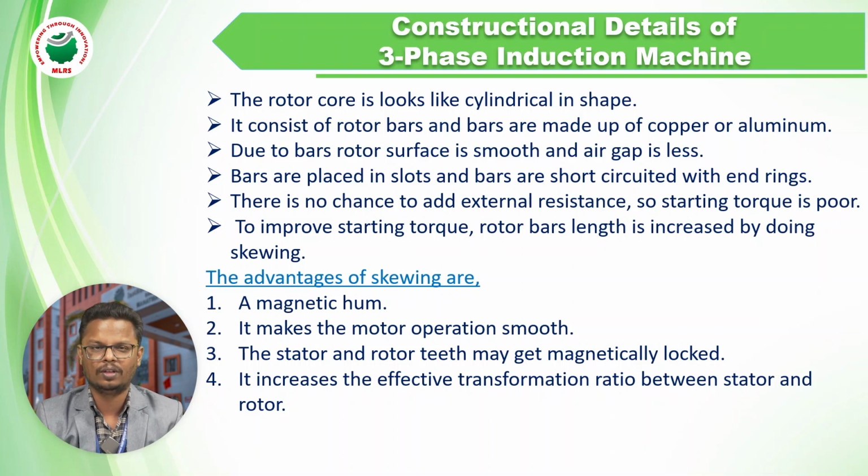And if we do the skewing, we have some advantages. The first advantage is reduced magnetic hum, which is nothing but noise. By doing this skewing, the noise of the motor will be less. The second one is smooth operation, so there will be no magnetic locking. Another one is that it increases the effective transformation ratio between stator and rotor. These are some advantages of skewing.